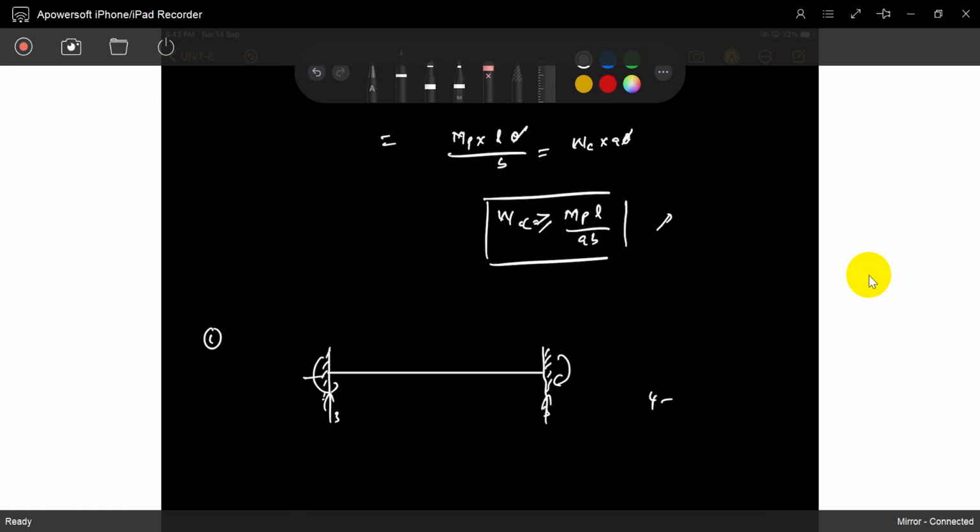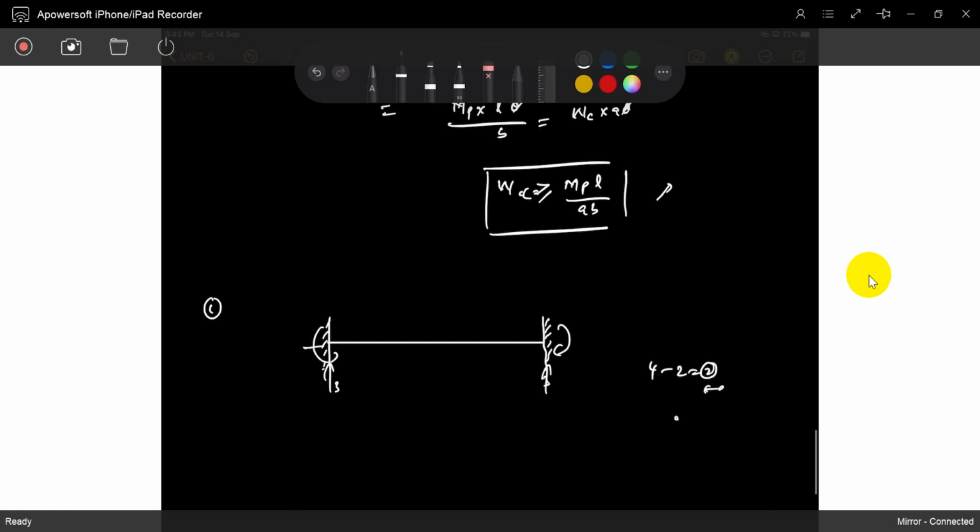And equilibrium equations also, you can delete the horizontal. Sigma x is equal to 0, delete it. 2. It is an indeterminacy of 2. We already know it, no need to discuss. So it is an indeterminacy of 2. That means we require 2 plus 1, 3 hinges are required to enter into the mechanism. Unstable situation, kinematic situation.